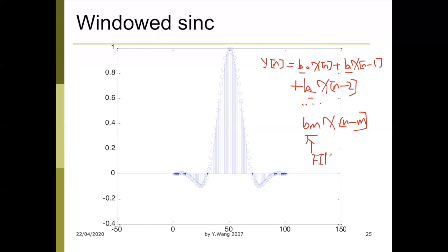I understand that this is a very broad domain, and different terminology comes up. So where does this coefficient link to this sinc function, when we design a filter and have this graphic representation? How that links to the coefficients is basically here. The value of the first point is b0. Then we have b1, then the third one is b2. So the filter kernel is basically a collection of the filter coefficients represented in a graphic way. The last one is your bm.